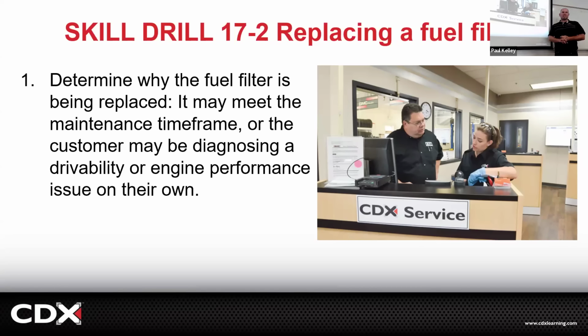Makes sense? But a lot of times back in the day, my dad would always be blaming the fuel filter for everything. He'd say, oh, it needs a new fuel filter. And I was like, your Blazer is stumbling intermittently. He's like, yeah, I think there's some junk in the fuel filter. Could it be anything other than the fuel filter? I think it's the fuel filter because if I punch it, all of a sudden it'll clear out and go. And I was sort of like, yeah, but if it was the fuel filter, it would run worse at wide open throttle. And he'd be like, yeah, it's junk in the fuel filter.